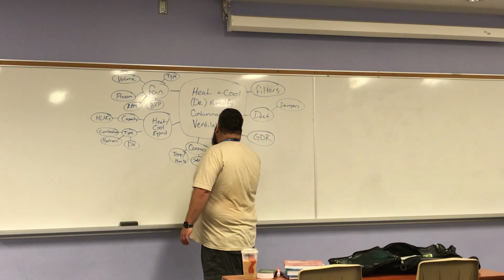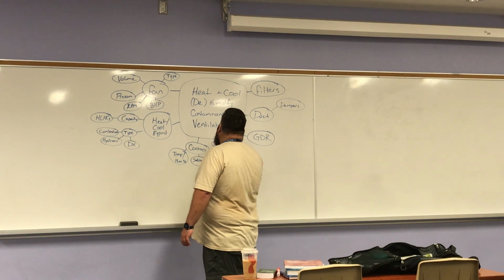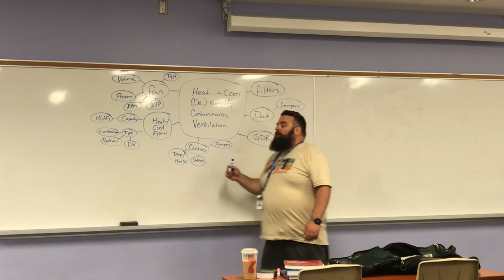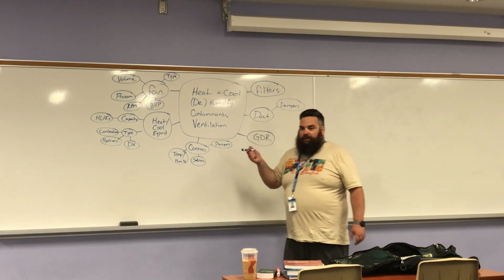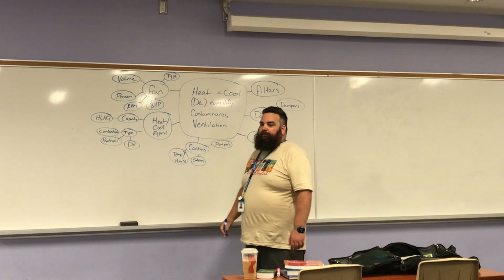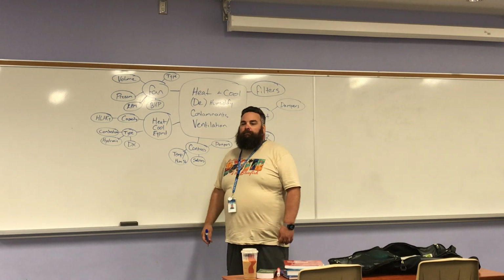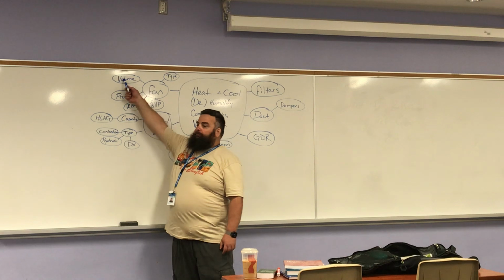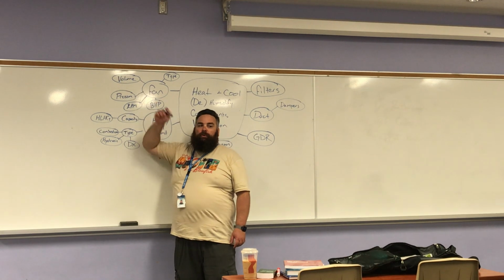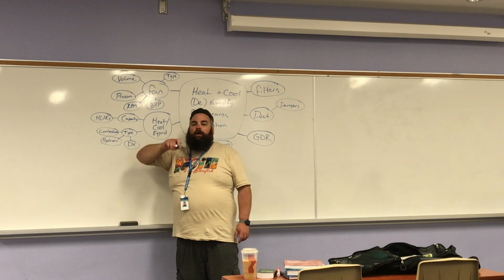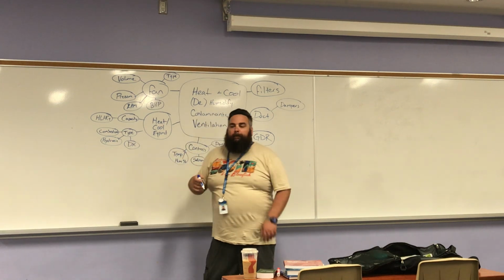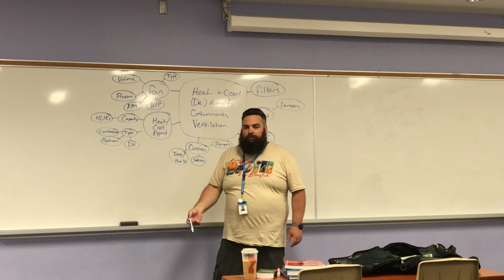Now, what do dampers do? Redirect airflow. Yes, they can redirect airflow. There's something else they can do. Open and close the duct. Cut off airflow. They'll control our volume, okay? They control our volume by imposing a pressure drop, okay?